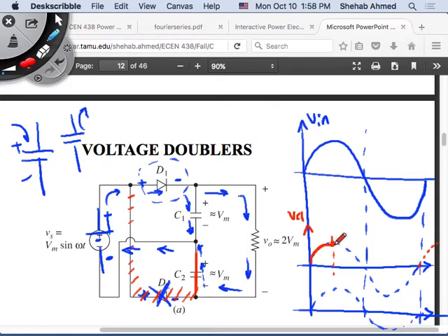In the half-wave rectifier, if I properly choose my capacitor to match my resistor value, I will discharge here, right? The capacitor voltage will go down, and then, in the next cycle, it will go back up again, right? Do you agree? Yes? No? Okay. And then the same thing with the other half-wave rectifier.